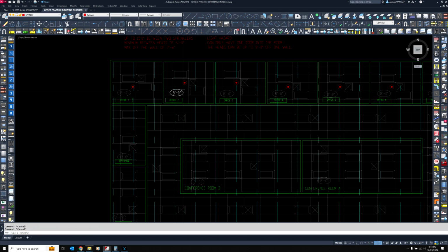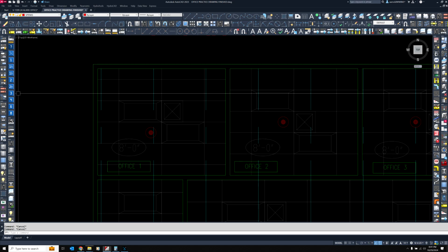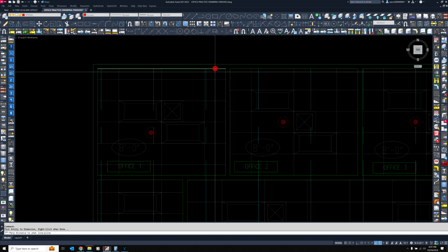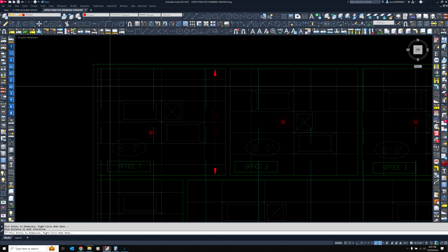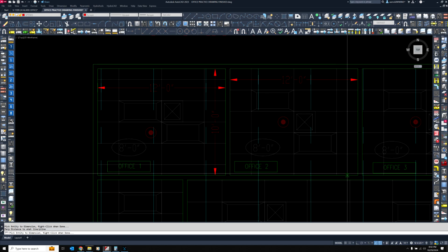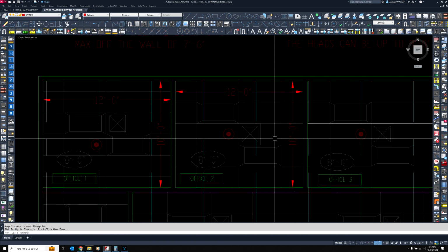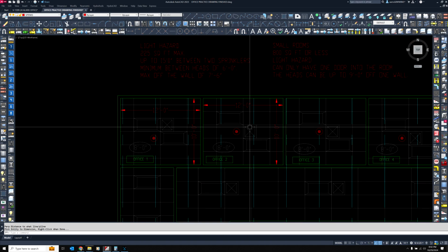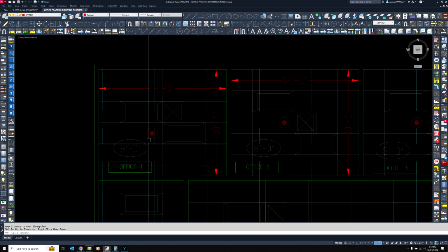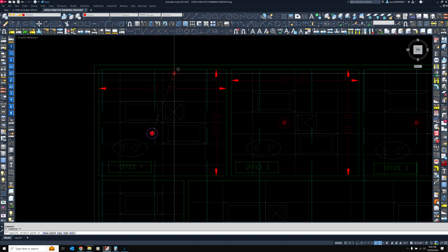Oh, you know what? We'll just use these rooms as they are. Alright, dimension. When you want to take a dimension, your auto dim button's right here. Left click, and we already know before these rooms are 10 by 12. So, what does that mean if these rooms are 10 by 12? Easy math, this room is 120 square feet. Does that mean this sprinkler head is protecting 120 square feet?